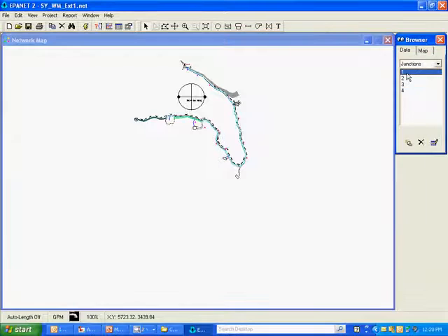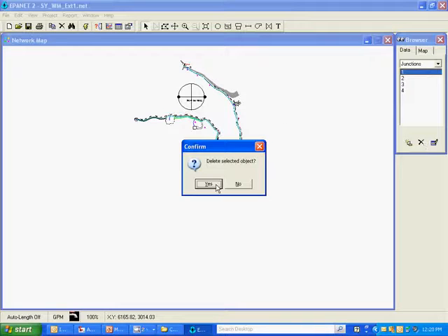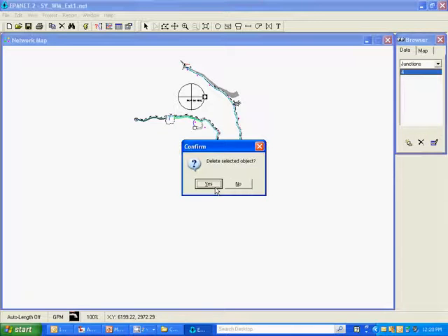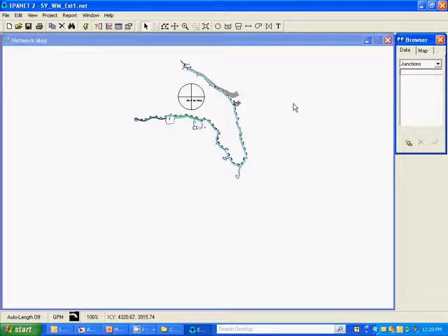I'm going to go ahead and delete all the nodes. The first node, 1 and 2, are the small pipe that I drew originally to test the scale. It's still there and we want to get rid of it. And the 3 and 4 are the ones I did second to verify the scale was correct. So let's go ahead and delete all of those. Otherwise we could get some issues with our model not knowing what to do with these unconnected pipes. And now we've got basically a clean model to start working with.